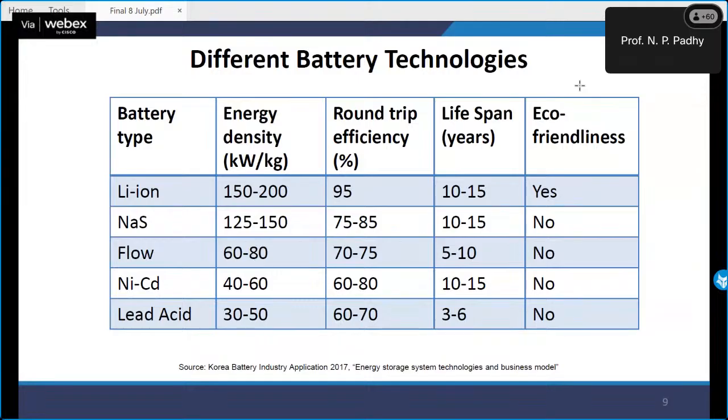So it is something like you have a load curve or a generation curve. When generation is more and load is less, I will charge my battery, and then discharge when my generation is low and load is more. So the battery is acting as a storage. So the pumped hydro storage plant, the mechanism is also similar to a battery, where it takes your energy during off-peak hours and generates during peak hours. So that is the philosophy. Hope you've understood. Is it clear now, the operation of pumped hydro storage power plants?